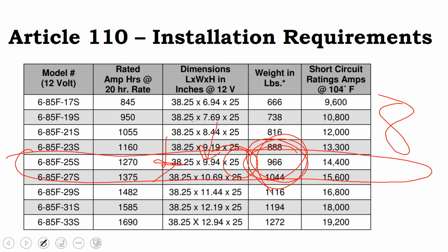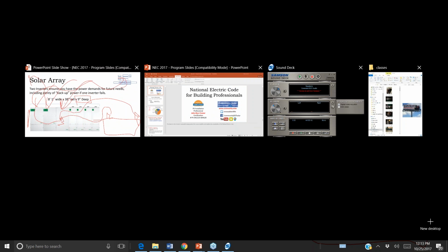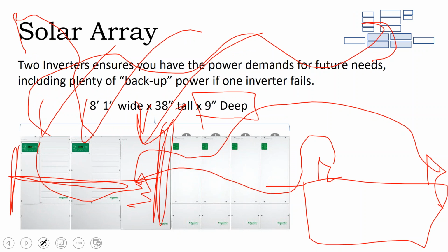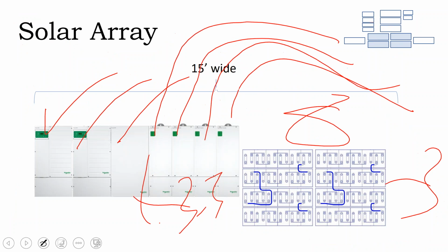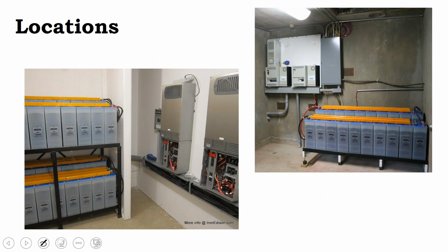So the off-grid battery systems can get quite large, or it might be that you have your Tesla Powerwall plus your solar inverter plus this integrated service panel, and at a bare minimum for an on-site kind of power wall for your on-site system, what you're looking at is at least 9 feet of dedicated working space. And that's assuming you're dealing with maintenance-free batteries. So, at least 9 feet of space on your wall, just make it an even 10, is a good layout for your future residential electrical room based on code.